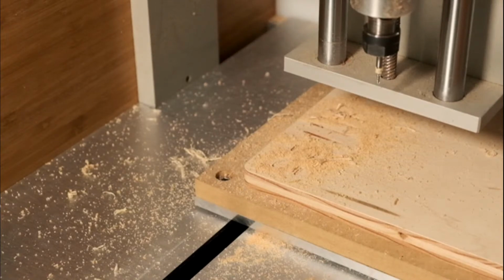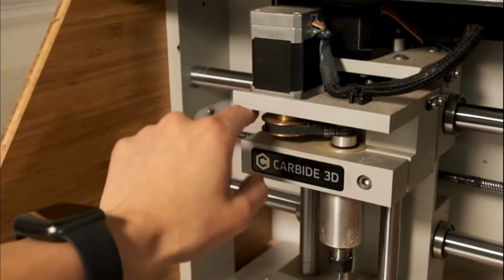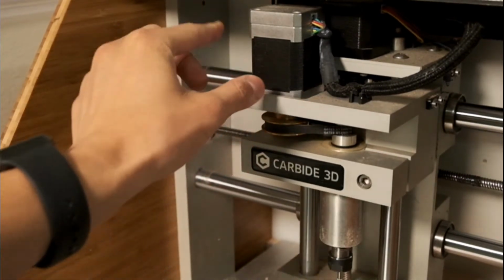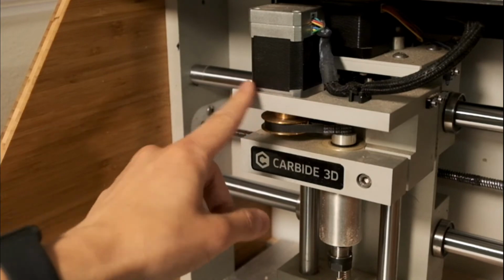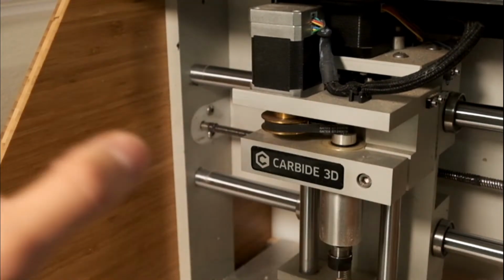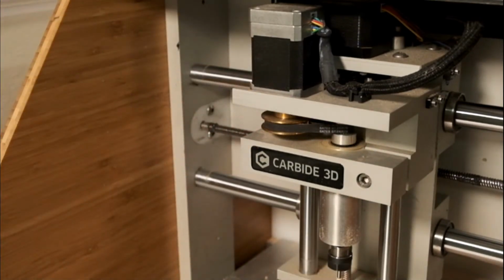I heard someone say stock movement. Is that confirmed? Can anyone corroborate that? For those of you that are asking, or that one person, this is a brushless DC motor. It's in a square NEMA form factor. It's not actually a stepper motor. It is a fully brushless spindle. Common misconception just because it's square, but you can actually get motors in that form factor.